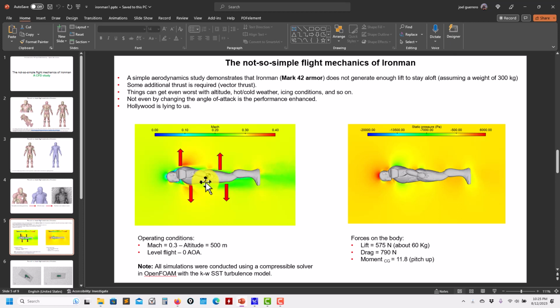So far I created a very primitive control system. It was an on-off: if the momentum is positive on here, off here, but it's not the actual one, we need to add a PID, which I'm working on, and it shouldn't be that difficult to put in. So the first part will be doing the polars. Here we have a fixed velocity or different velocities, then we change the angle of attack. We have our conditions, weight, and so on. And then we also compute the momentum and everything, and with that we can construct a small model and test our PID system, but also we are going to get a good idea about the aerodynamics.